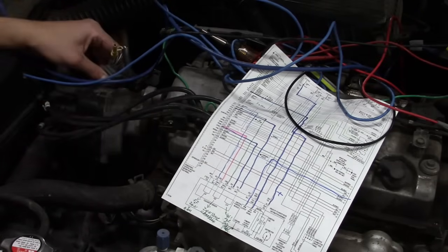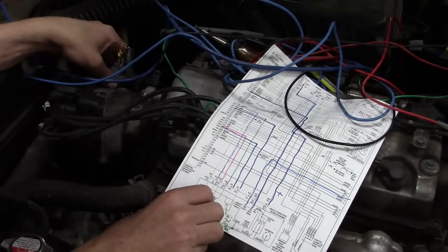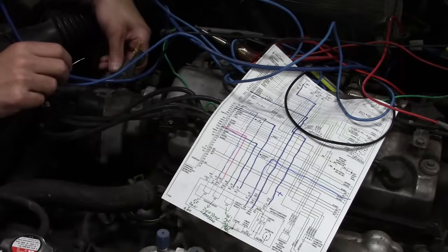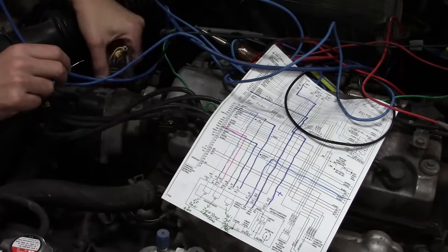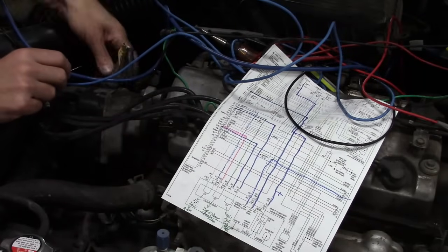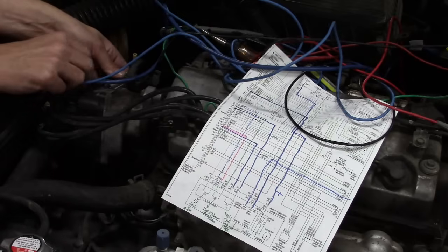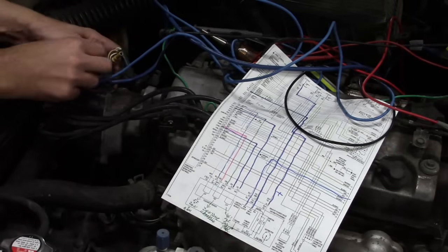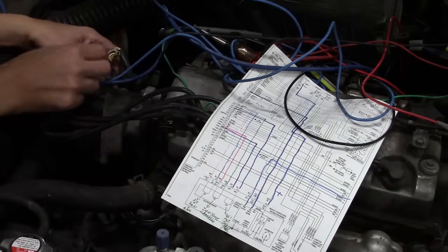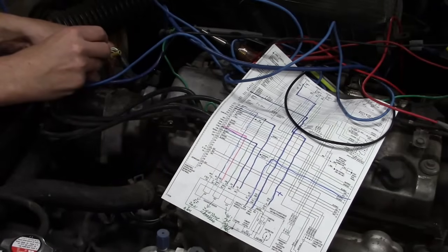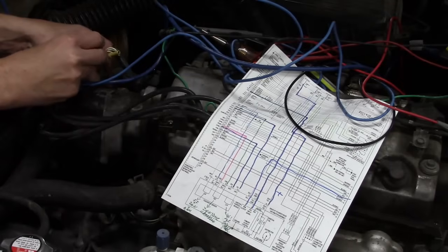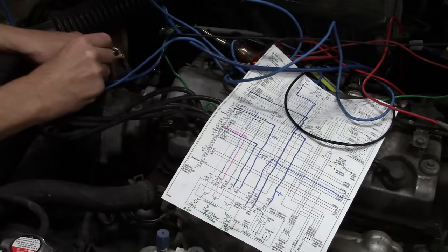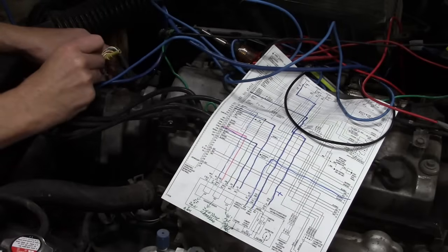Going to probe him. And then the other one on the TDC is going to be a green wire coming in that transitions to orange and blue. Where is a green wire coming in? There's a green wire coming in, second from the right, and there is an orange and blue coming out. That would be him. All right. So now we've got our TDC connector probed.